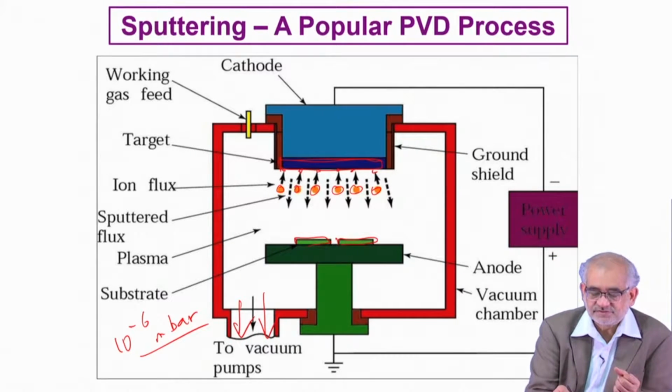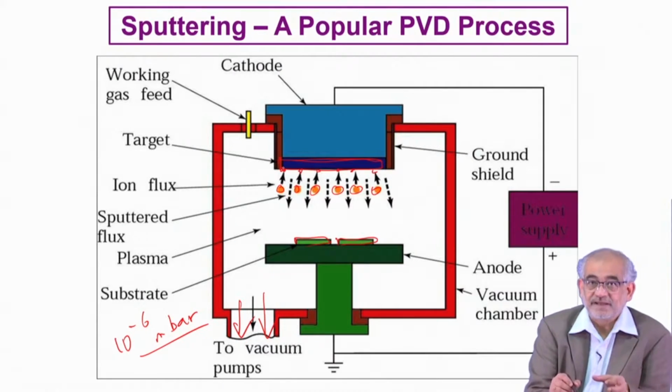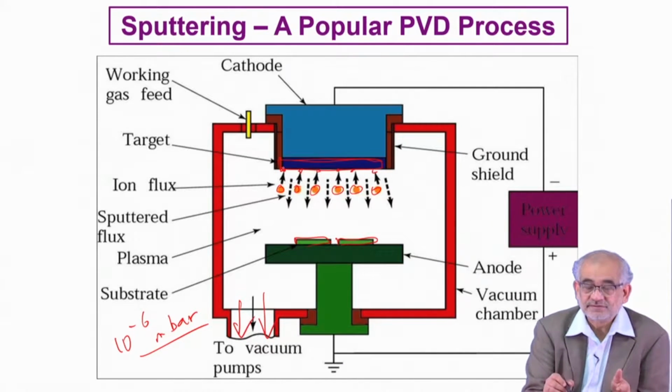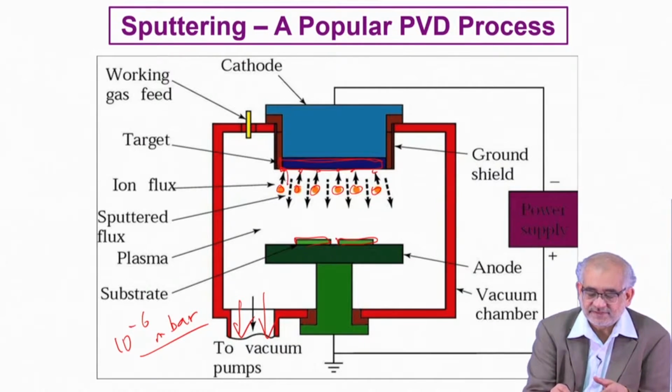So when these atoms are hit by these projectiles, individual argon ions, some of them will experience an impact with an energy that can overcome the binding energy of the atom to the surface. That allows those few atoms to get detached from the surface.